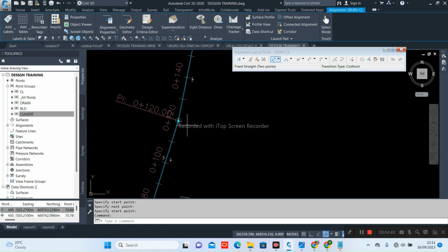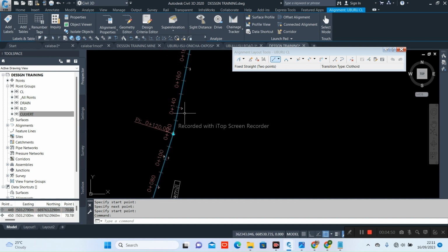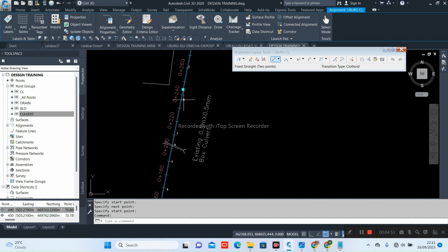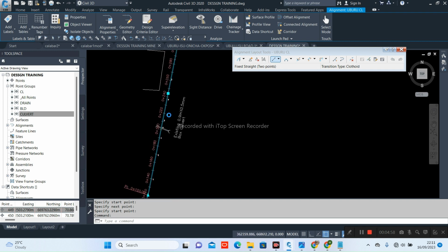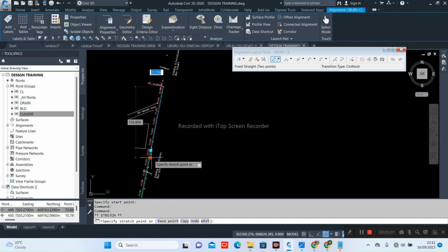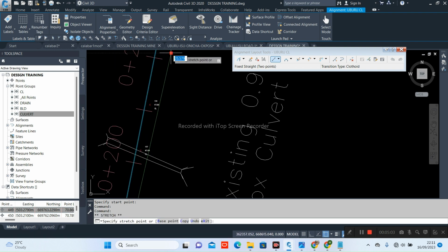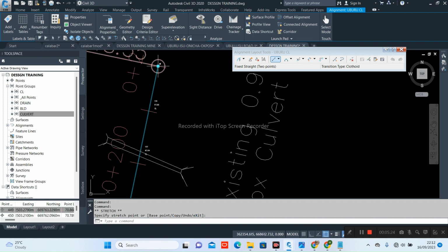So we have this. So we can now do well. Look at this, we have an issue here. You can bring it here because this is the culvert and ideally we are supposed to be at the middle of the culvert. Sometimes it will not be ideal at the middle. What you just do is use the surveyor's idea to guide yourself. Sometimes it may not be at the middle because the culvert may be longer on one side than the other. So you just go by what the surveyor gave you as center line.